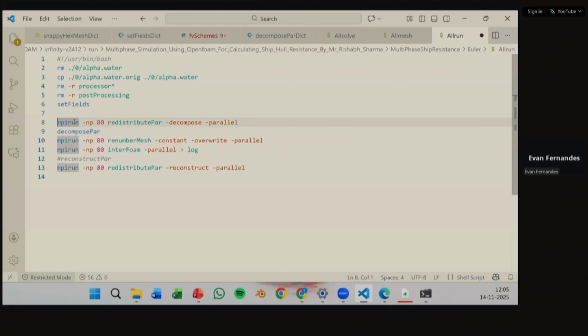comment this one. So we'll keep this, because when you're running any of the Crank Nicolson or any of those particular cases, now in Eulerian, these particular commands run fine. But in your Crank Nicolson, the local cases, it gives an error. Okay. It won't give an error, but it just gets stuck at finalizing parallel and all that thing.